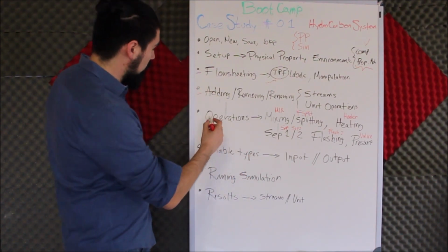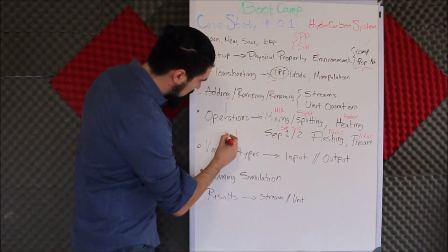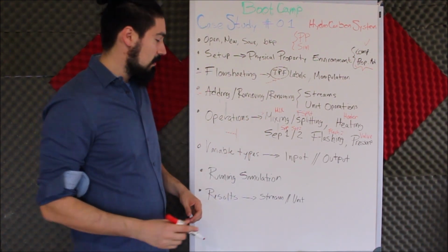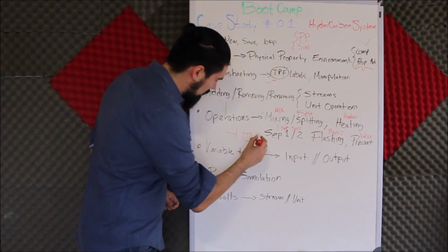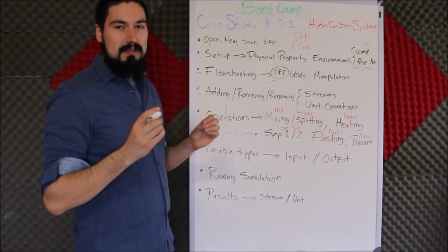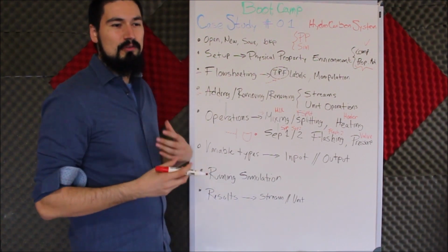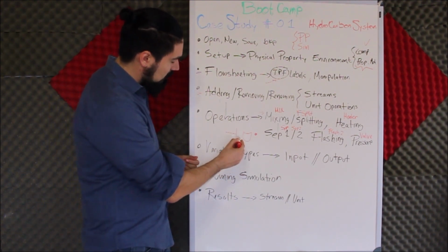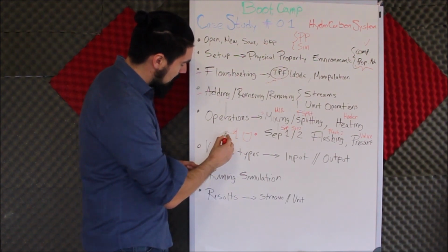For instance, if we're talking about a mixer, even though you may draw this as a tee mixing, or this may be a tank of mixing, or even just a physical point, for Aspen Plus, the mixing unit is always the same. This is just for us to understand, to see if we're working with a T unit that maybe two streams come here and they mix.